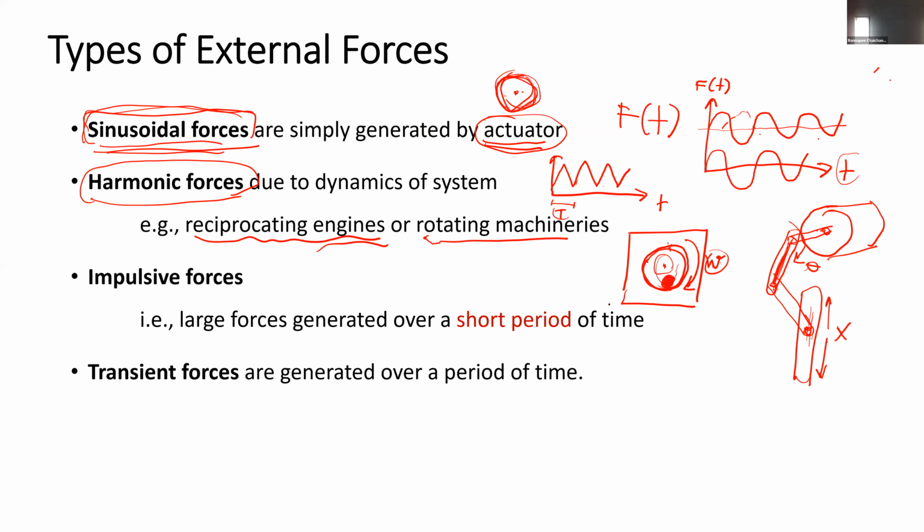If you put this machine on a scale, you can read the scale change depending on time when the washing machine rotates, and the force goes up and down. It can create vibration, and this kind of vibration is also a harmonic force with a constant period relating to the angular velocity of the rotation.